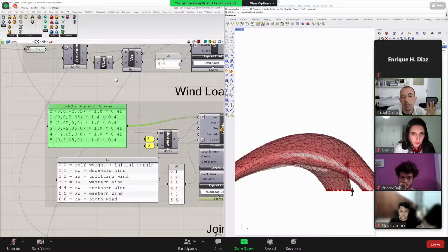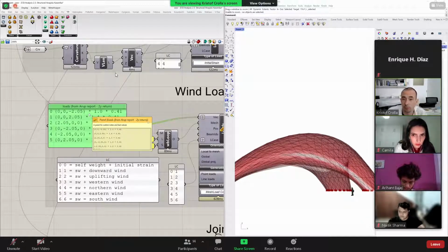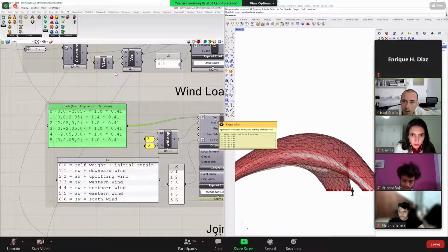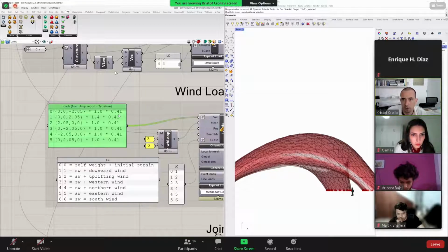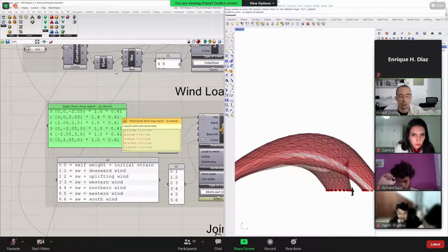And here you see in the Hong Kong building code, that's where they specify that we only need to work with 2.05. Is it Newton per square meter or kilonewton per square meter? I'm actually, kilonewton per square meter. That goes in. And in Hong Kong's building code for temporary pavilions, we can work with a reduction factor of 0.41, because otherwise you're calculating with the 5-year storm, and this is calculating with the 100-year storm or something like that. So that's why we have a reduction value.